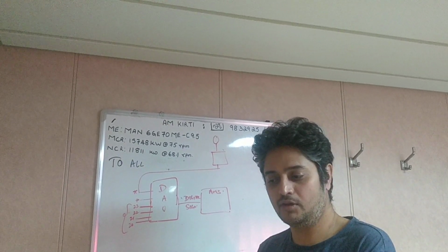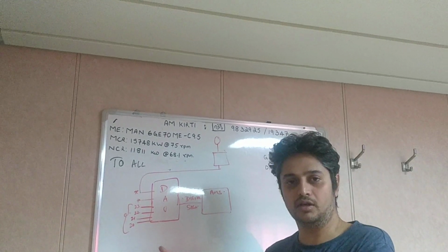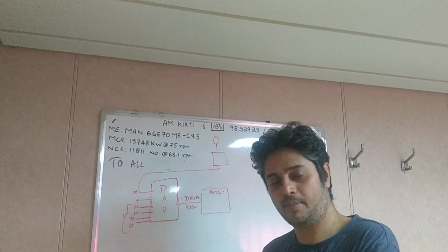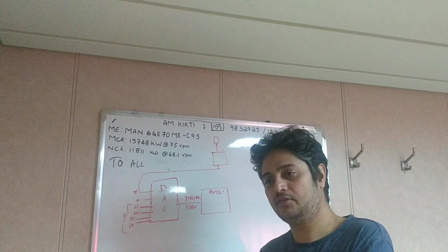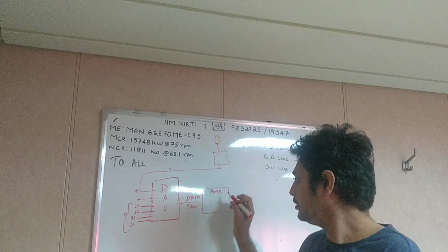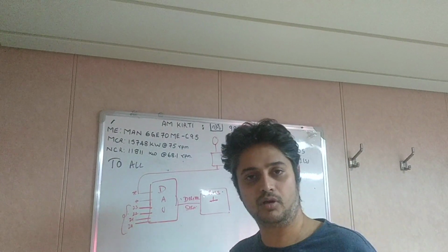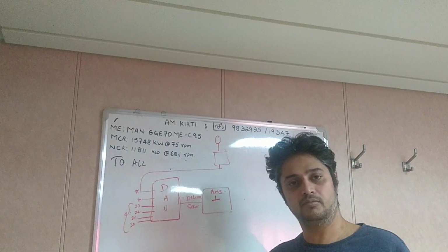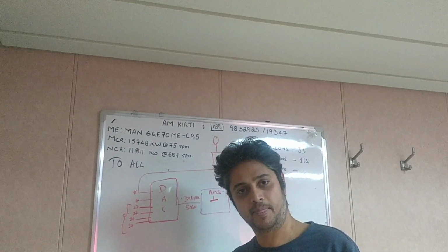Sometimes you will observe the electrician requesting the chief engineer that he wants to inhibit one alarm. There are two ways of inhibiting. One is by making, here you will have an option when you want the alarm to come, that AMS will ask whether you want the alarm to come when it is in NO condition or when it is in NC condition.